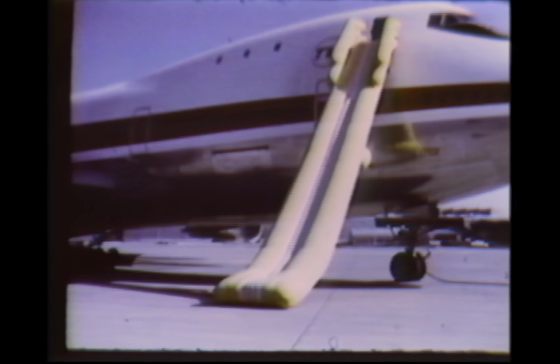To use the evacuation slide, pull the release handle toward you. Then lift the container and push the slide overboard. The slide should inflate automatically. Go out with your head low, step to the edge of the platform, and enter the slide. If the evacuation slide does not inflate automatically, lift this cover and push down firmly on the lever to inflate the slide. One other exit is located in the cockpit, an overhead escape hatch.